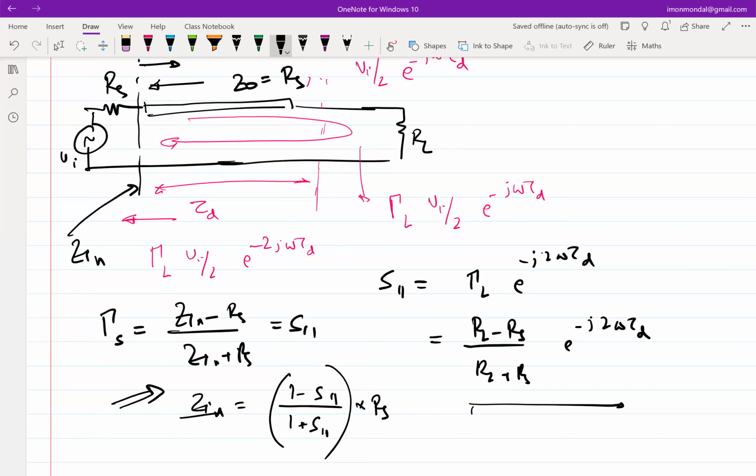This calibration cycle is essentially telling the PNA, hey, I have connected some things now, so recalibrate whatever you think is the amount of delay this set of wires is giving you. It sends a test signal and sees when it comes back. From there, it finds the effective tau d, and then it recalibrates.